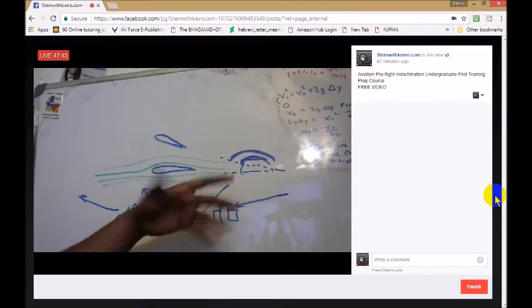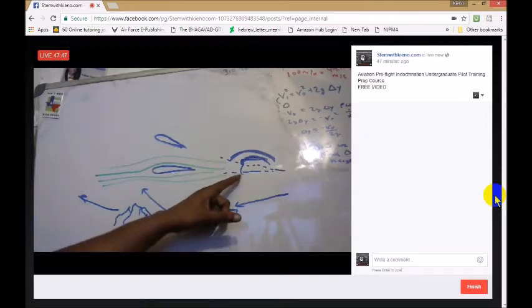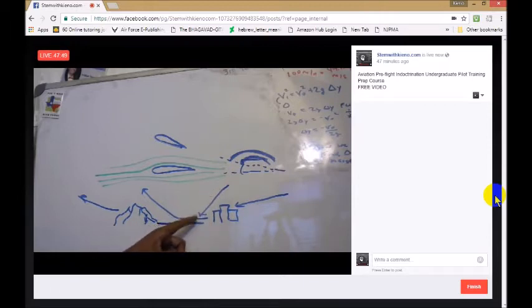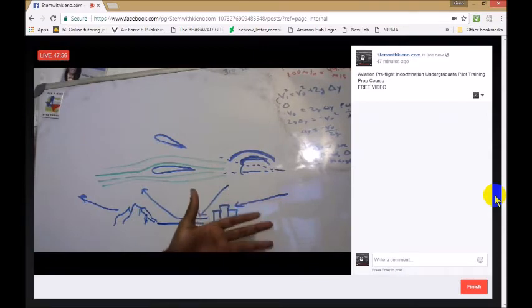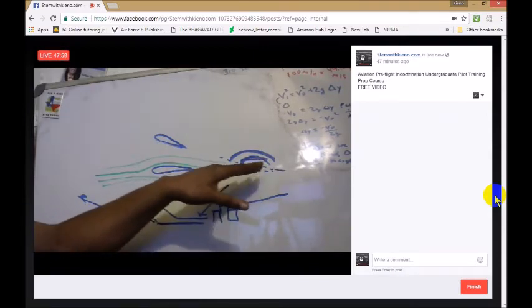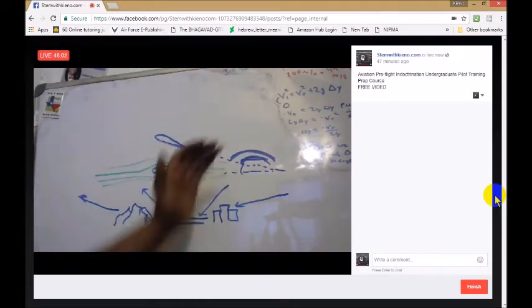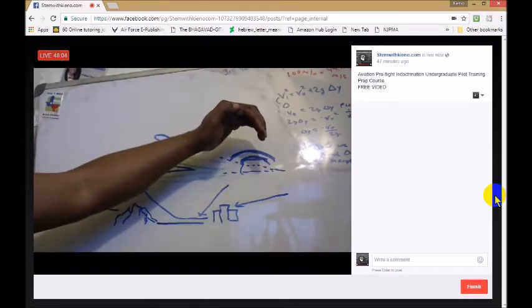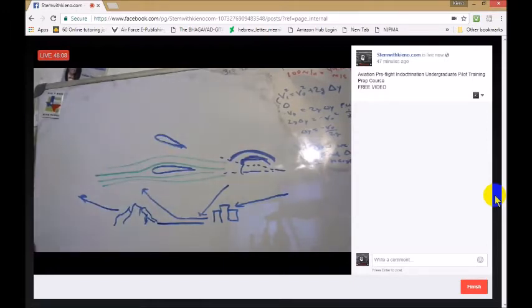So when we extend our flaps and our slats, we can increase our angle of descent without increasing airspeed, because without slats and flaps, we would have to come in at a higher airspeed. When we put the drag in, we get slower, we generate more lift, but we also generate more drag. And so our wing is more curved, and this helps us generate a higher amount of lift at a slower airspeed. So that's what slats and flaps are for.